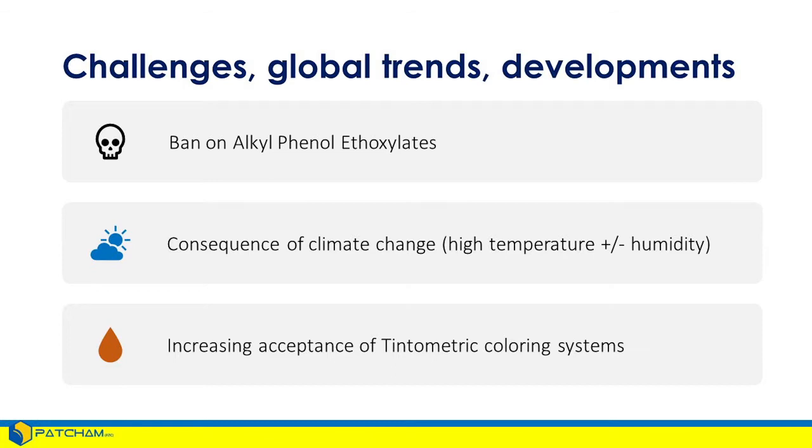Well, when we switch to waterborne, water has a very, very high caloric demand for evaporation, and its evaporation rate is dependent on relative humidity, which is then the impact of temperature and the amount of moisture that's in the air. So the higher the moisture content in the air at a certain temperature, the lower the evaporation rate. So this really impacts then the film formation of these waterborne coatings.